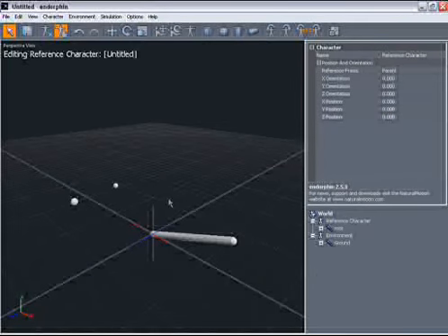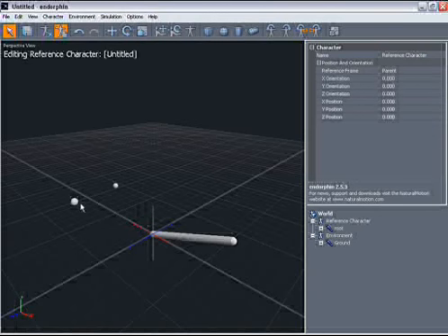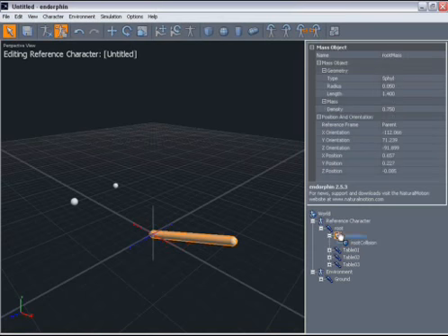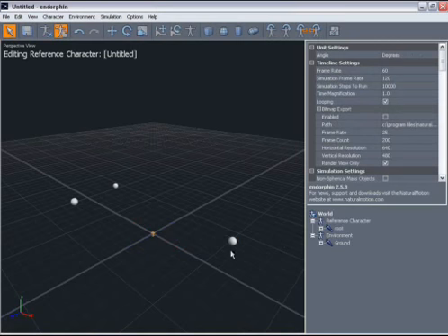Now this doesn't look much like a table at the moment, but each of these 3 sections here is one of the joints with associated mass objects. If we go over to the node view, we can see that under the single root joint object now, we have 3 other joints and a mass object. We're not going to need this long mass object, which is the child of the root joint, so let's select it in the viewport and click delete.